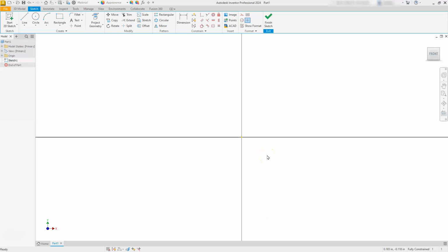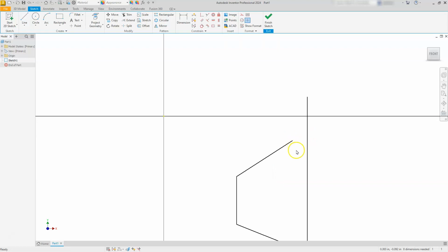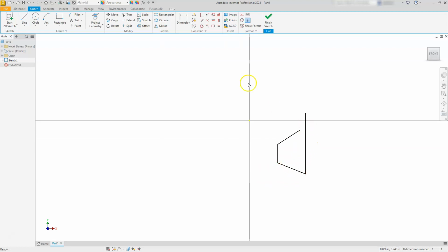Now keep in mind that this thing is going to be incredibly small. So some of the first things I'm going to do is just create that shape, right? I'm going to draw a line, and of course I'm going to make it as big as I can. All right, so I'm just going to create a sketch here, and one of the things I do like about Inventor is that I don't have to be too accurate here in the beginning, meaning that you can see that I overshot this one, but a coincidence constraint will go ahead and correct that problem for us.